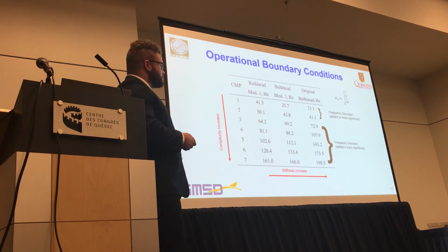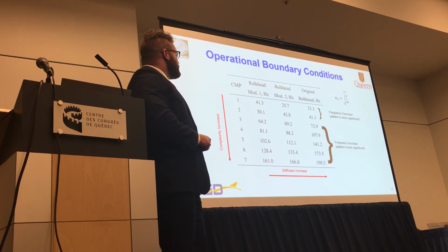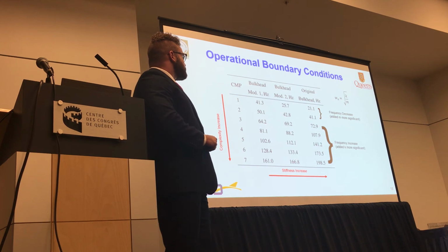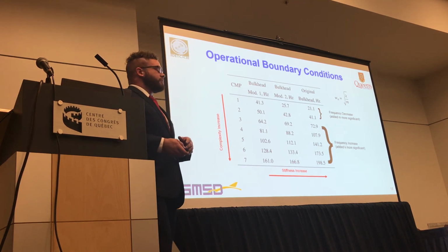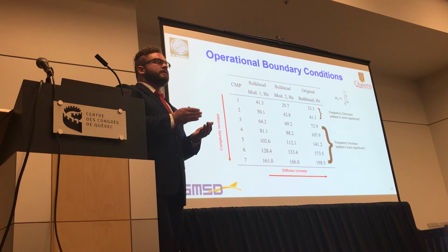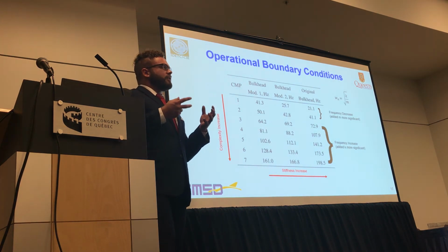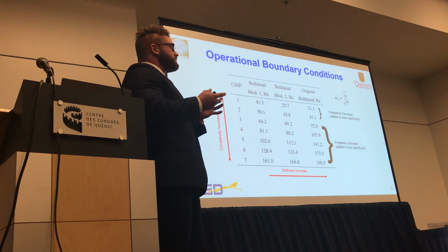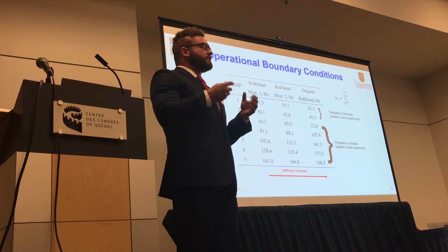And then I wanted to address one more point, that the frequency increase is not consistent. As you can see, there's a pretty small increase here, whereas some of these increases are on the order of 30 to 40%. So it's important to keep in mind that the frequency increase will be inconsistent from mode to mode, and it has a large relationship with where you add the stiffener in correspondence to the modally active regions of that particular mode shape.